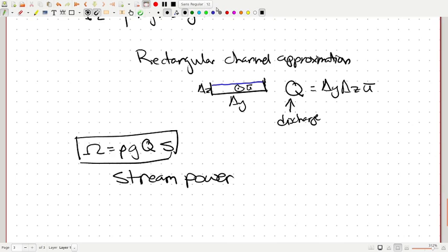And I'm just going to, as a little reminder, note that basal shear stress in the river is equal to rho g h for depth, times slope, and so that's also pretty similar, right? And I didn't explicitly mention it this time, but the way I was able to remove the kinetic energy conversion, or potential energy conversion into kinetic energy related to flow velocity or sediment motion.